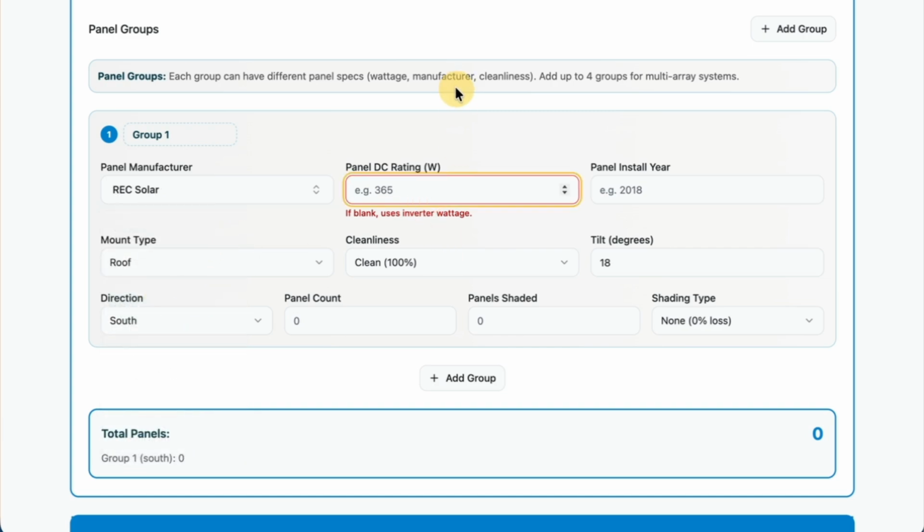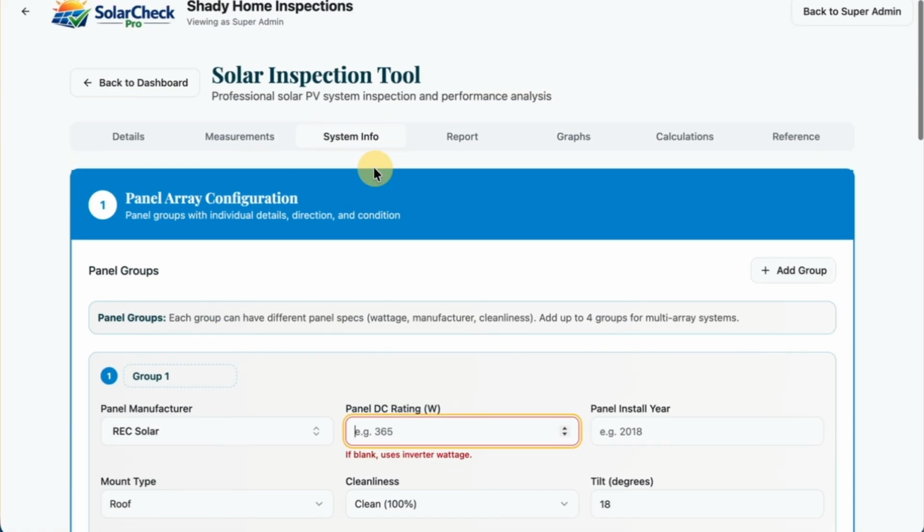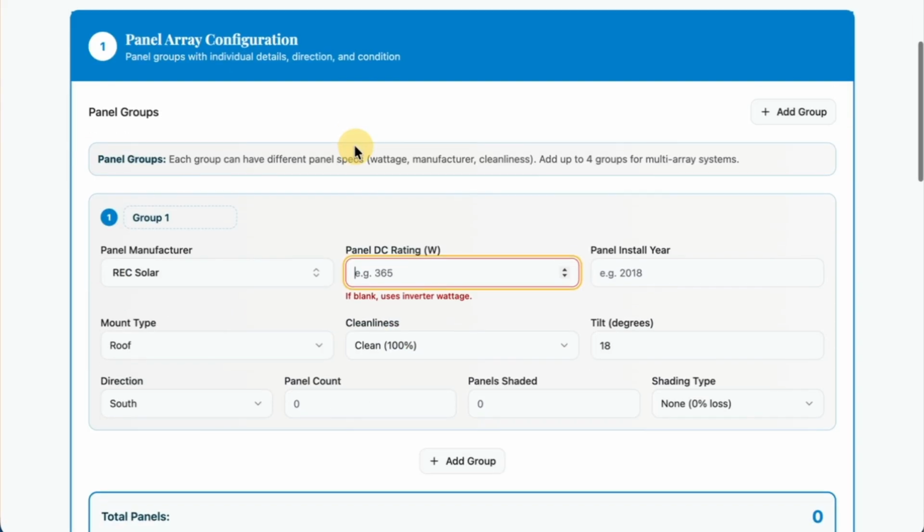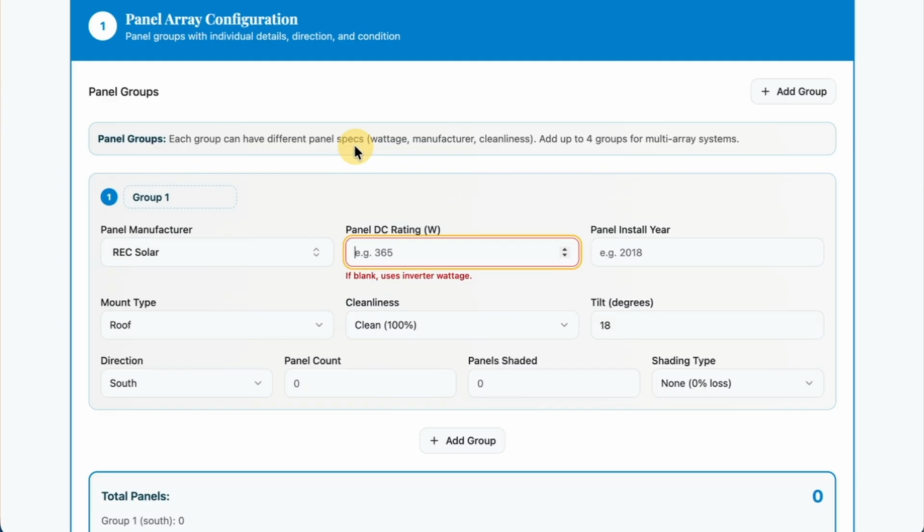A lot of this is going to be found on the nameplate, but as we recommend, if you can gather solar docs information before you get on site, I even like to go ahead and put in a lot of the client information and the address, and all of that is done. And then if I have solar docs to back up a lot of this stuff, I can go ahead and put that all in there when I'm on the computer. And then when I'm on the job site, it's really just verification. I've reduced the workload a lot by gathering that information up front. But if you do find yourself having to gather this information off of the data tags on site, you're going to do that when you're up on the roof.